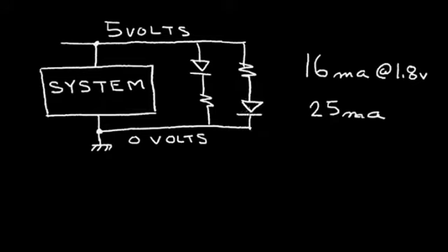Either way should work, and this has perhaps a very slight disadvantage in that I have a little higher voltage at the LED. Here I have 5 volts, and here I have a little less than 5 volts. In this case, my LED has a cathode at ground, so it's a little lower voltage. And since the LED is going to be on the front panel, I think I'd prefer to put a little lower voltage at the front panel.